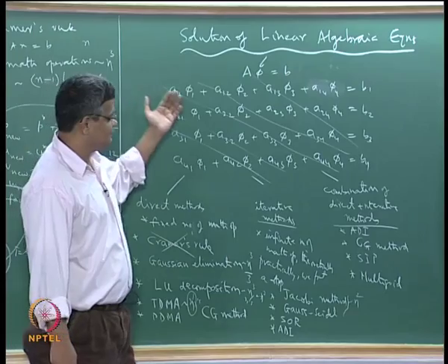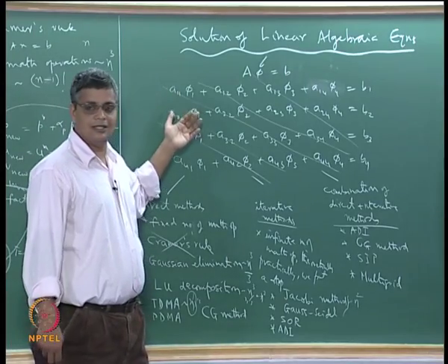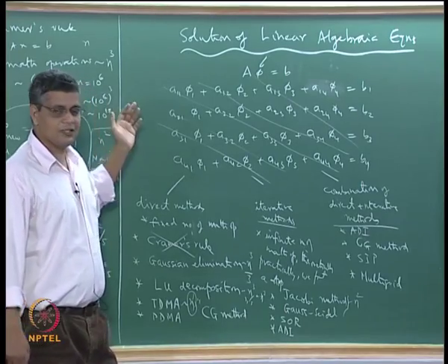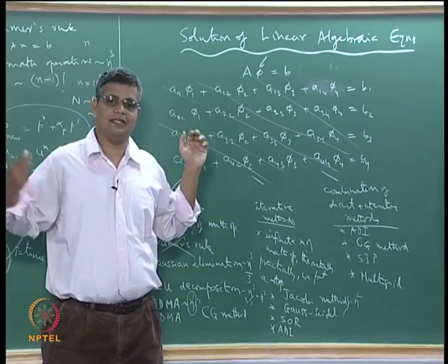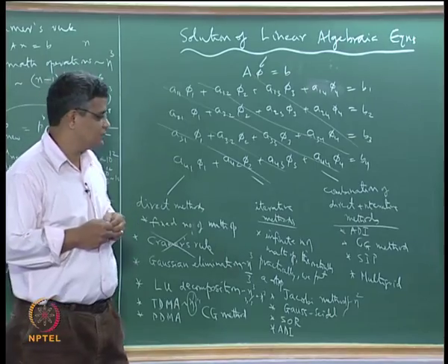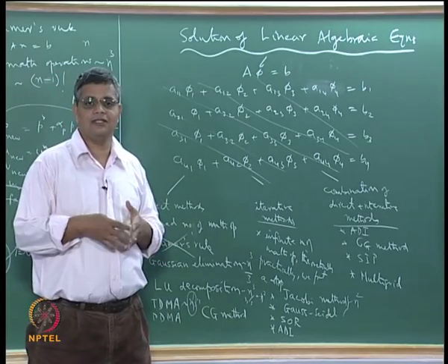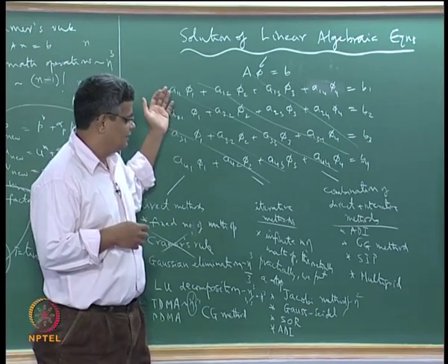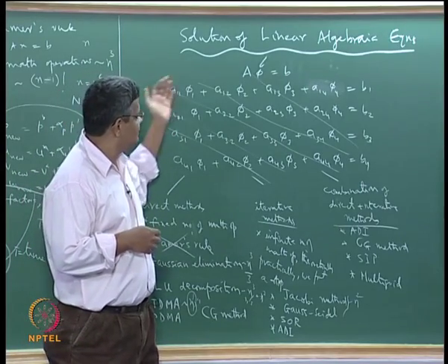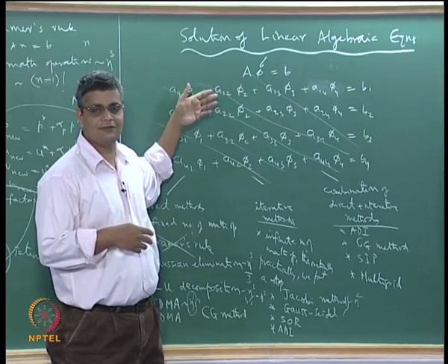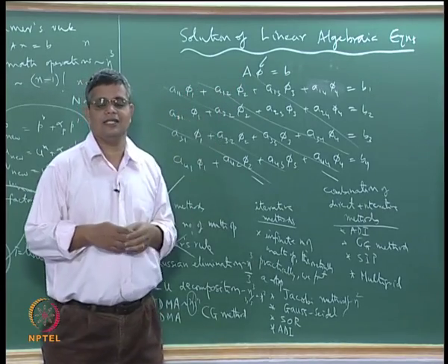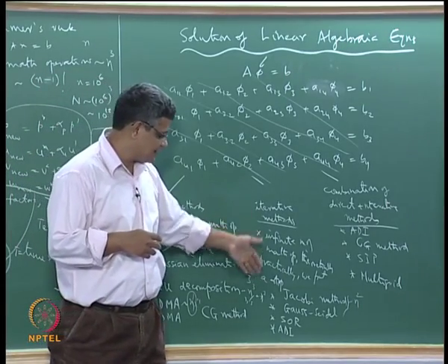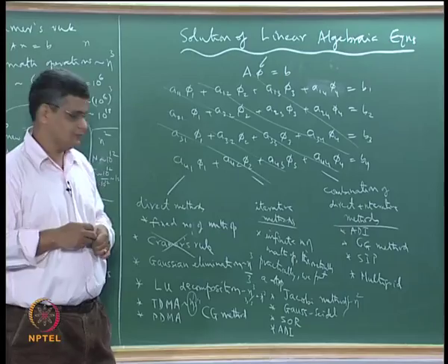So these methods will work in the context of CFD for a convection diffusion equation of the generic scalar transport type on an orthogonal coordinate system. On a non-orthogonal coordinate system, the resulting discretized equations will not satisfy the diagonal dominance conditions, and in such a case these methods cannot be applied.